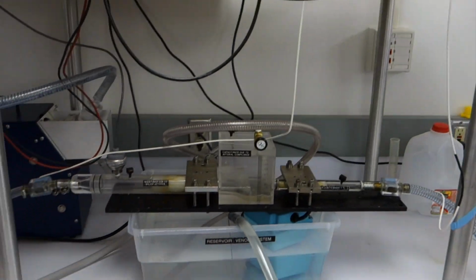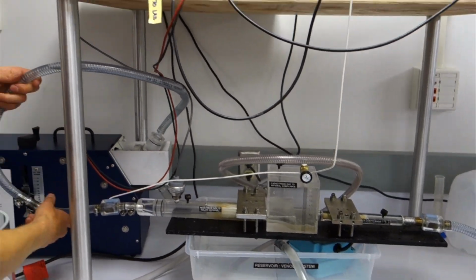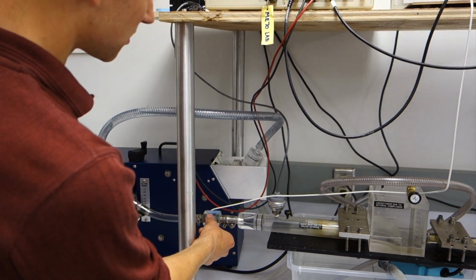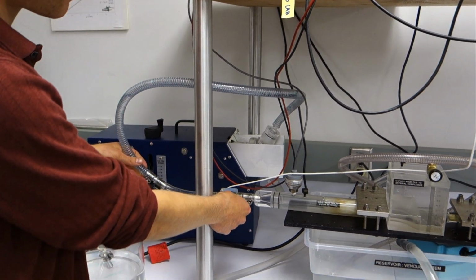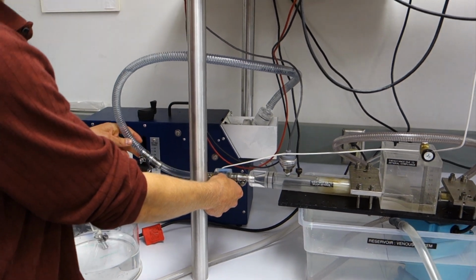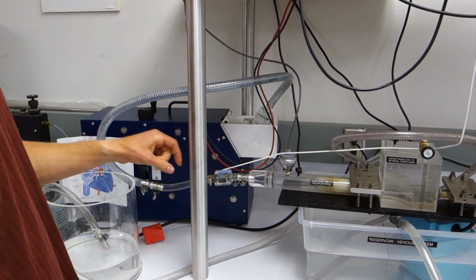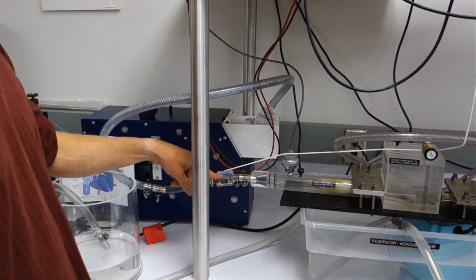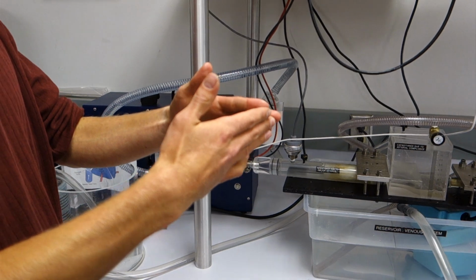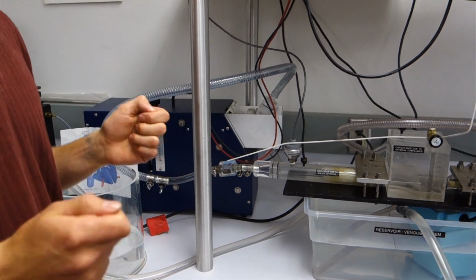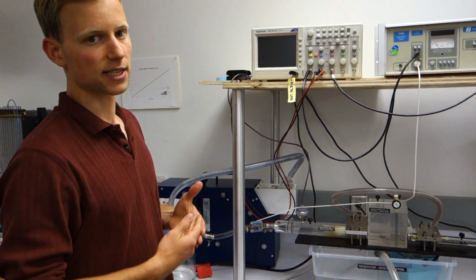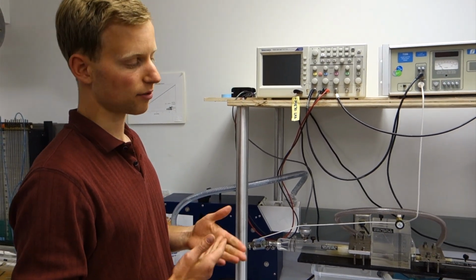All right, working our way further before we turn it on. I know it's tempting to turn it on, but it's nice to look at what we're going to be doing first. This is a flow sensor. We've actually talked about these flow sensors before in this lab, in the flow measurement lab. This is an ultrasonic transit time flow sensor. We have 2 transducers and a reflector, and the transducers send signals across the flow, and then depending on the time difference that those signals are received, we can back out what the velocity of the medium is going to be. And they're nice because we get instantaneous unsteady flow rate values.